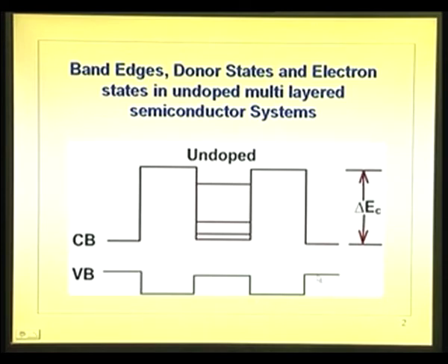So, what we did is show a diagram, a heterostructure where both are undoped. Okay. So, gallium aluminum arsenide, probably undoped. So, conduction band is there, valence band is there, and how much the band gap is depends upon the aluminum content. It can vary from low value to high value there. And this one is the gallium arsenide, or the narrower band gap material. Here we are not specifying what the material is. So, this is the conduction band, this is the valence band.